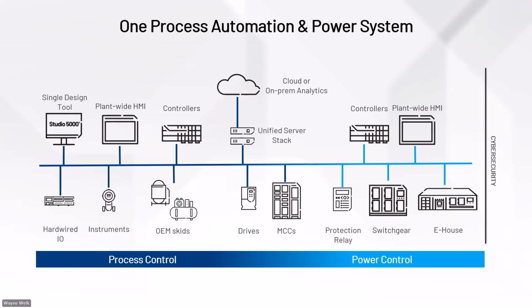So let's say you had a pump not turn on. Well, that's connected to a motor that maybe a starter is connected to. It's in the MCC. What if you were networked to that MCC, and that soft start had detailed information about what caused that trip? In an intelligent power system, you'd be able to see that information from the plant-wide HMI, and presumably have a much shorter unplanned downtime situation, because that operator has more information in front of him to more quickly troubleshoot that issue.